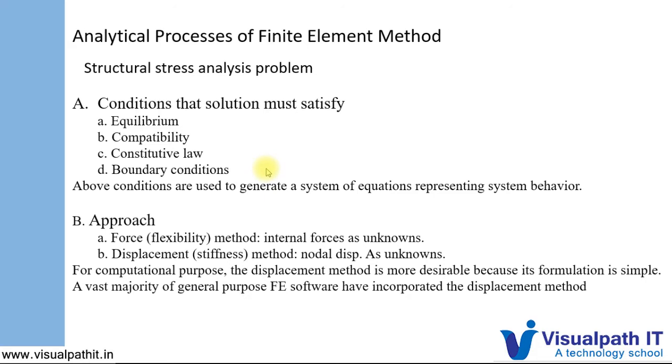Boundary conditions involve, for example, if some loads are acting on the geometry or the geometry is fixed at some places, the corresponding boundary condition needs to be included as a part of those equations. Then only our system will behave like the actual physics applied on that body. And once we have formulated the equations, we need to solve them, right? Without solving, we will not get our desired displacement or stress.